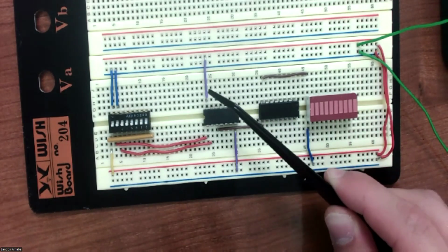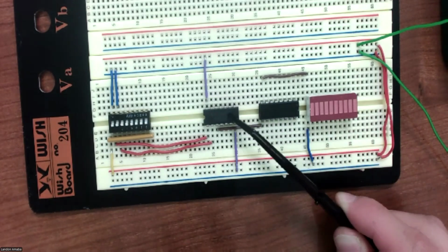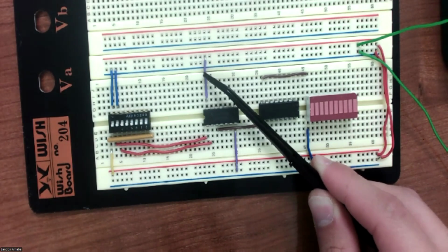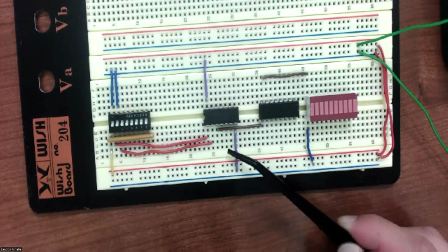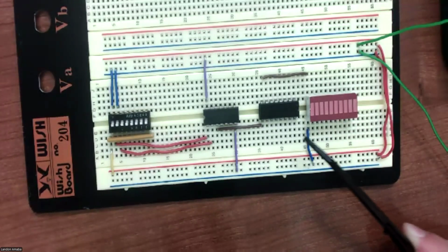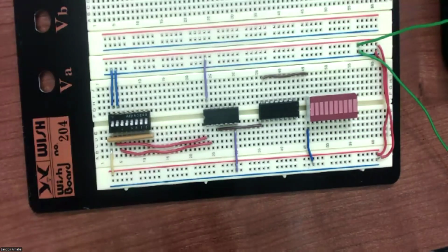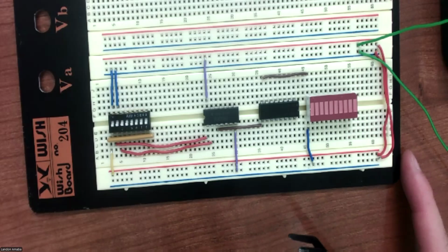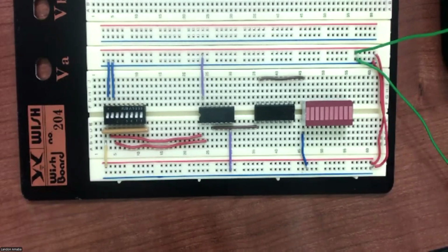Make sure for all of your ICs, for your gates, make sure that it's sufficiently powered with power and ground here. Make sure to always use a resistor as to protect your LED package, and so none of these LEDs explode or burn out unintentionally. So that was a quick review about how these components should be done on a breadboard, and make sure to look out for any other videos regarding the switch and LED schematics.